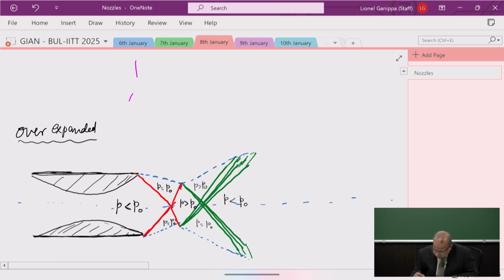Now, what we see here again, at the intersection point, interactions will take place. A fan interacting with the free boundary will result in an unlike reflection. Unlike reflections will lead to an oblique shock of the same family generating there, coalescing to form a strong oblique shock.